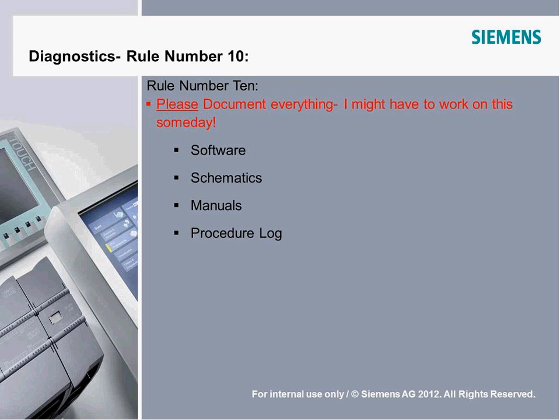Another question. Why would you use 4 to 20 over 0 to 10 analog? And actually, there is a lot of 0 to 10 out there. 99% of the time I'd prefer to see 4 to 20. 4 to 20 milliamps as opposed to 0 to 10 volts is just a better industrial design signal. First of all, with 0 to 10 volt, 0 is a valid number. So if you break a wire and you're at the end actuator and you're measuring a voltage out there, 0 volts, you don't know whether the wire's broken or it's actually just sending a 0 signal.